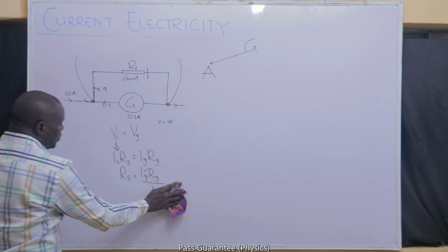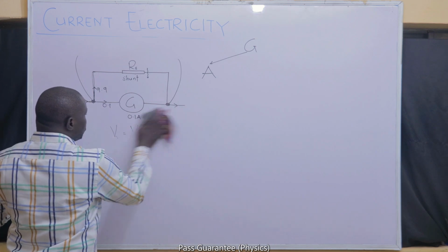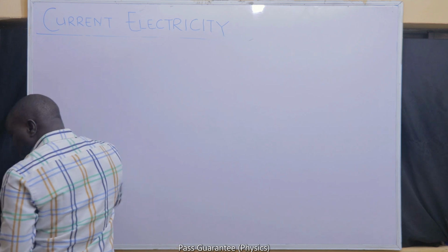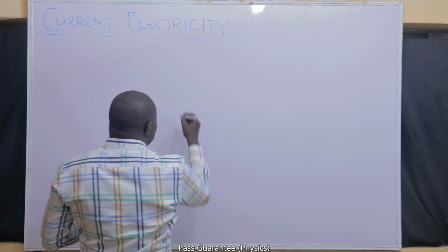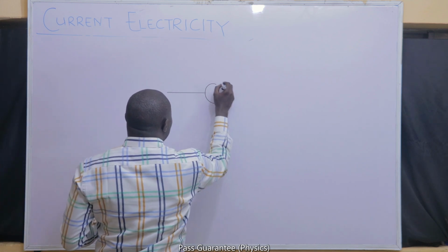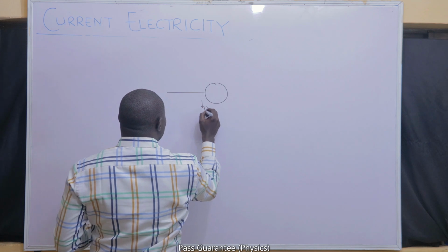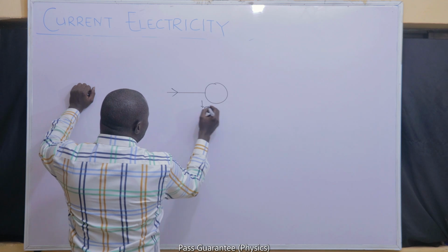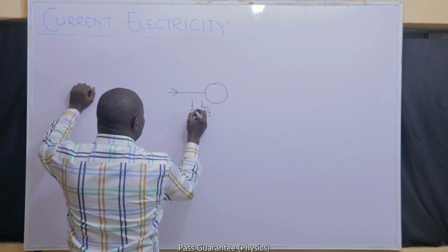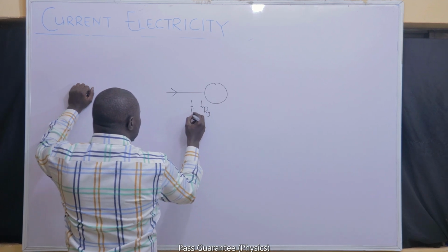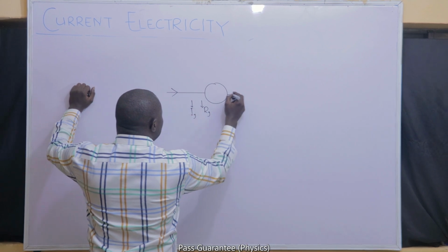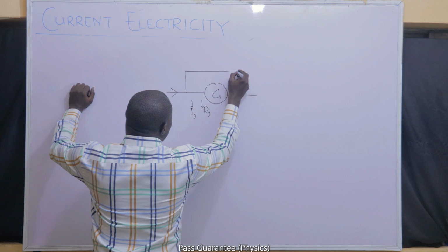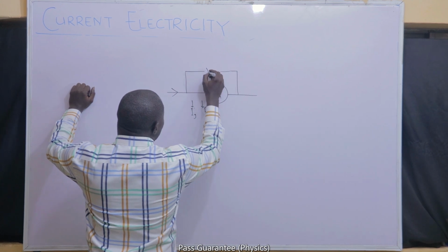How can I convert the galvanometer to a voltmeter? Galvanometers generally have a very low resistance, and the current that is expected to pass through them is also very low. So if we find the potential difference across the galvanometer, it is usually also very low.